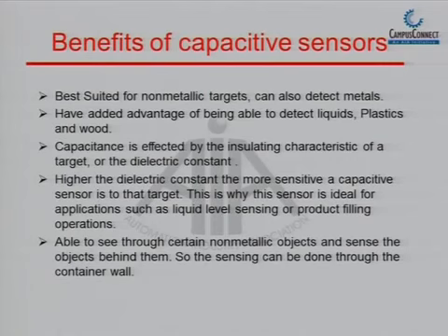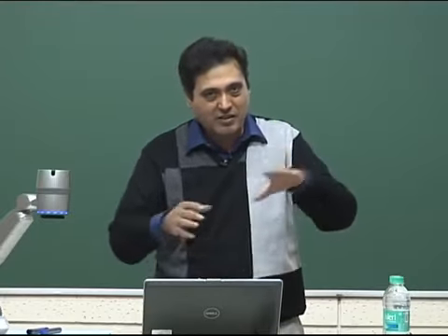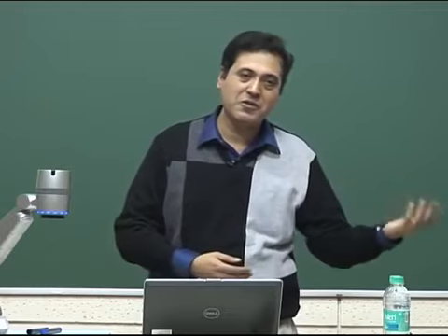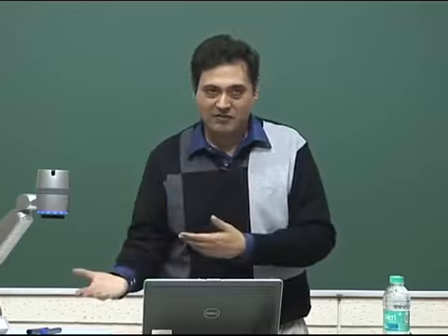Now, that air gap cannot be detected using an inductive sensor or a photo sensor unless you have a weighing based system. So, for that purpose they use a small capacitive sensor. The capacitive sensor acts as one plate, and the air gap, that is a hollow gap, can be used to get the target, to detect whether the pouch is empty or filled up.